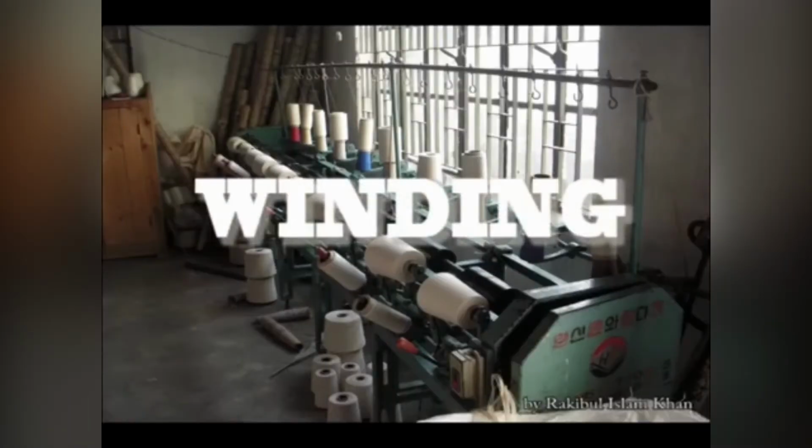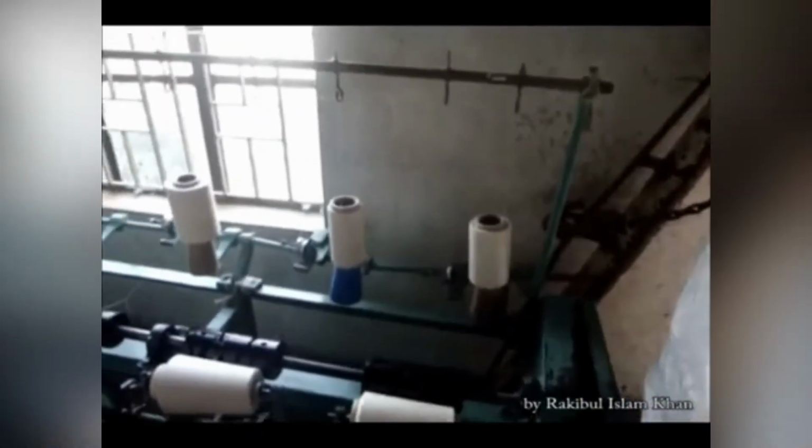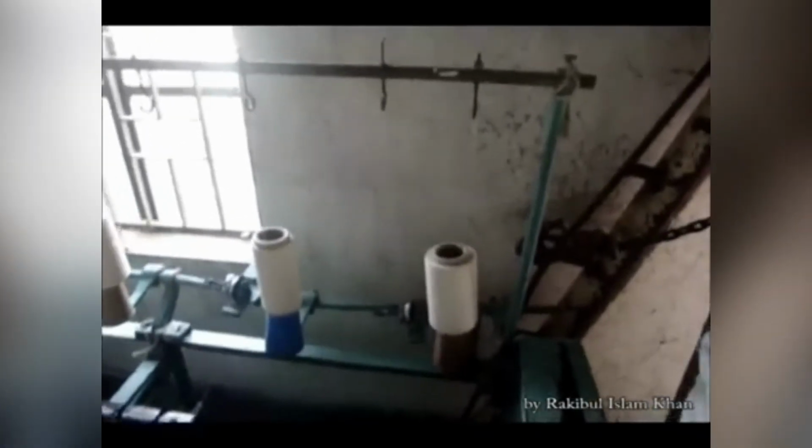Winding is the process of transferring yarn from one package to another suitable package. Usually yarn from the spinning mill comes in the form of cone. To prepare the weft yarn, the yarn from the cone package is transferred to pirn package so that it can be set in the shuttle of the shuttle loom. This is done by the process of winding.